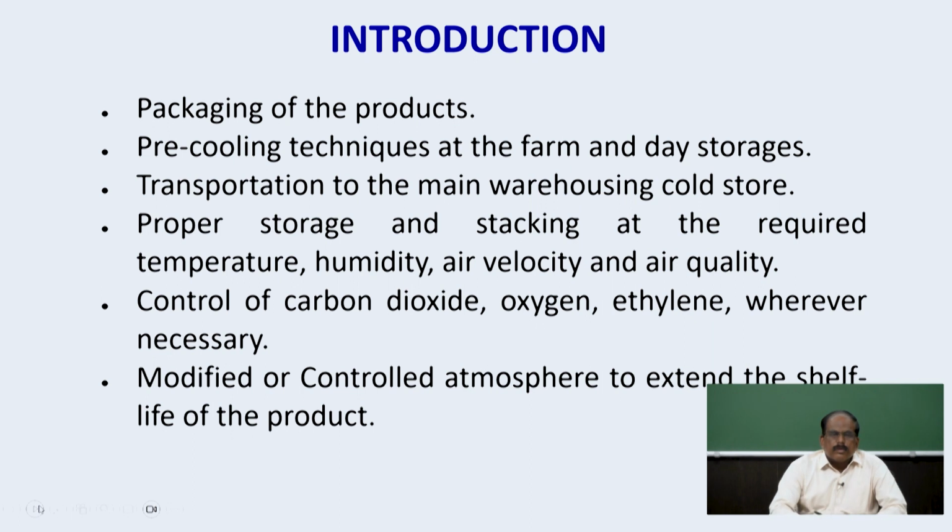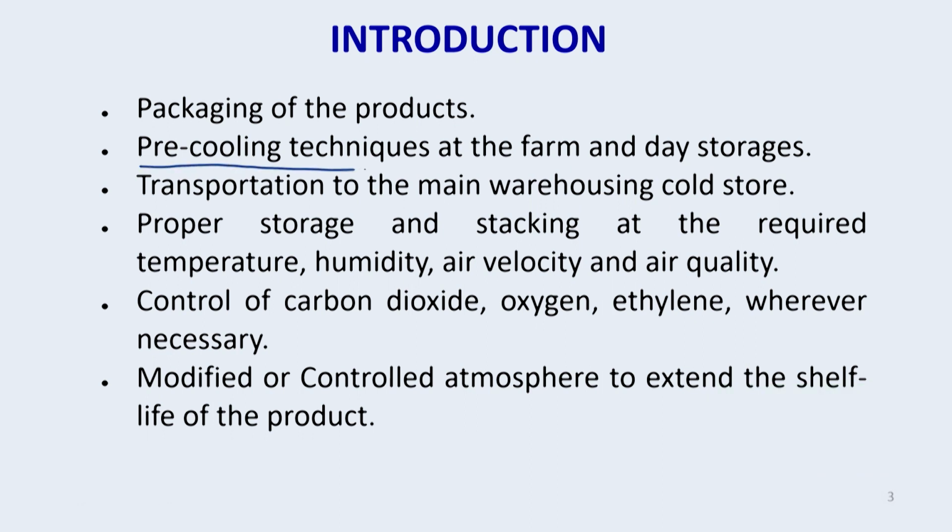Packaging of the product is very, very important. In the subsequent slides, we'll be discussing controlled atmosphere and modified atmosphere. Pre-cooling techniques at the farm, and the farm and day storages. As I have explained in one of the earlier lectures, if there is a delay in the pre-cooling process by 1 hour, then the shelf life of the particular product could be reduced by close to 1 day, or 18 to 24 hours. This is based on the assumption that the ambient condition is around 35 degrees centigrade.